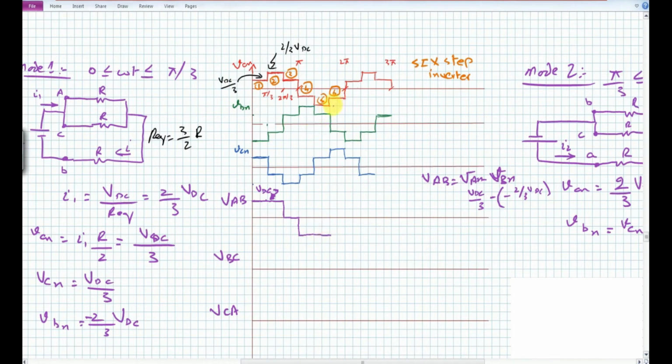In here we have again these two values equal in magnitude, and therefore they will cancel each other. So we will again see this type of a waveform. So we have an output which toggles between VDC, minus VDC, and 0. So we have actually a 3-stage output available between the phases.